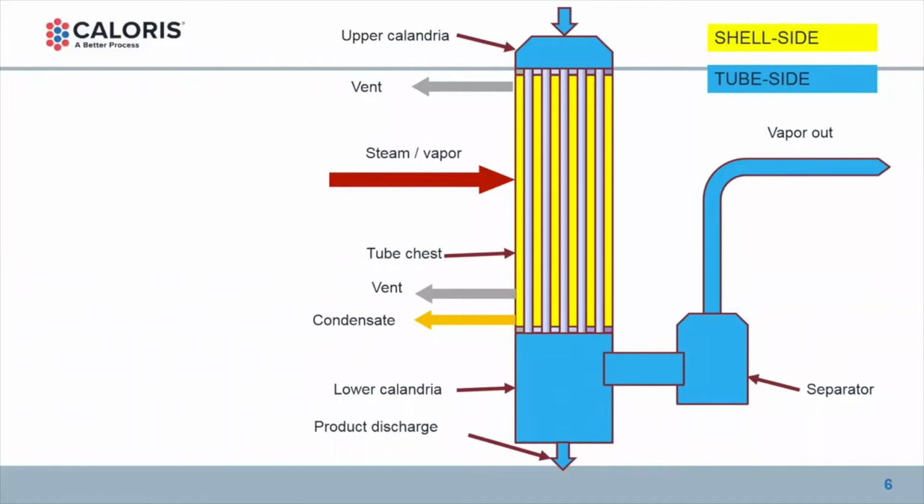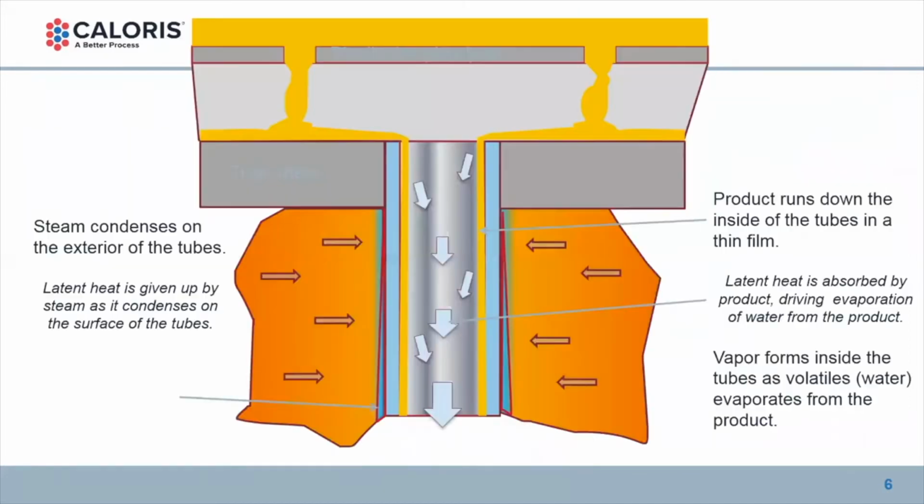And if this were a forced circulation evaporator, those tubes would be flooded instead of the falling film design here. Getting into the falling film design, ideally the yellow liquid coming in the top is at product boiling temperature as it enters. And it's distributed so it flows down the inside of a tube.